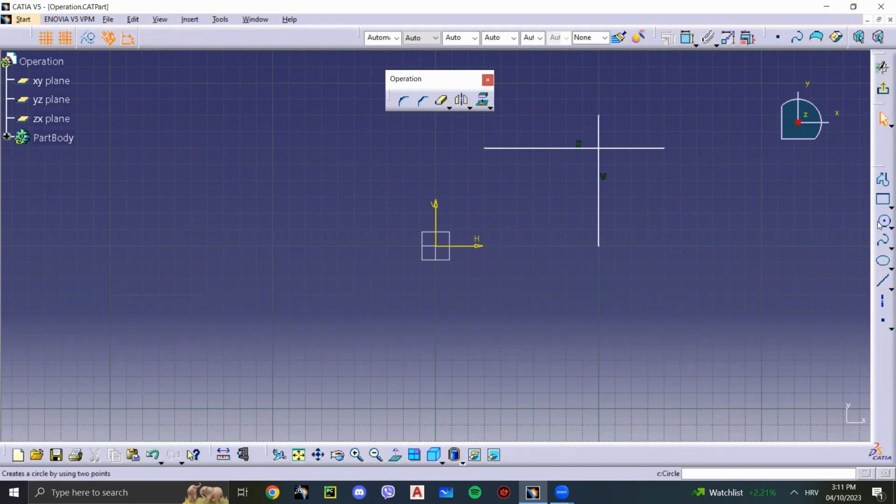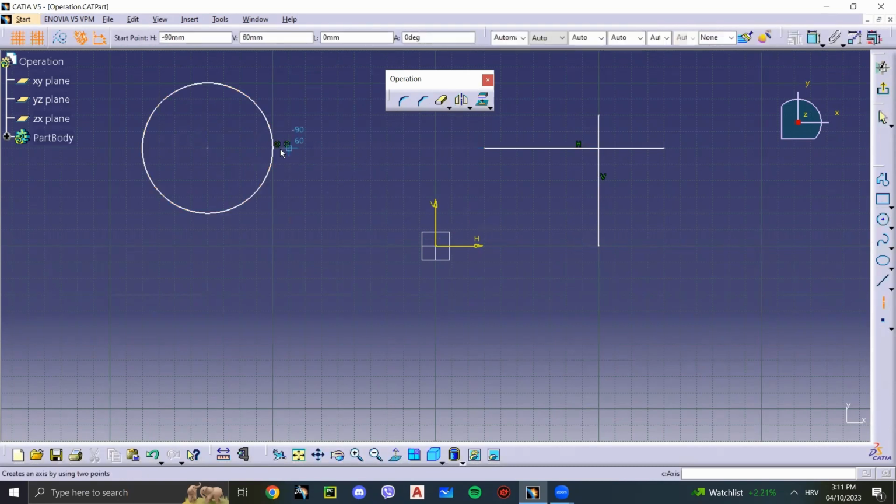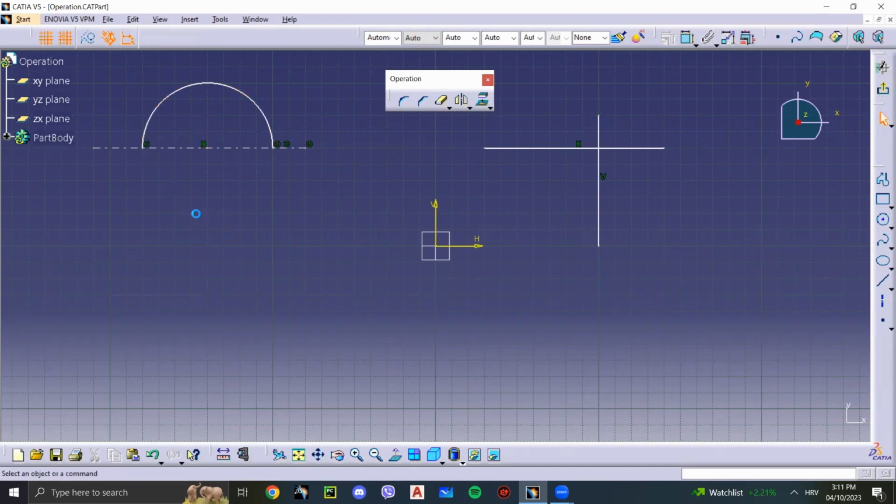Let's say you want half a circle, but you don't want to use the command arc to make it. You can do it like this. Get a construction line. Do this. Now we got two halves of a circle, and we can trim one side. There we go. We want a quarter? That can be done as well. A quarter circle is right here. There we go.